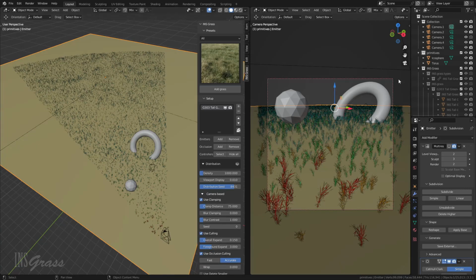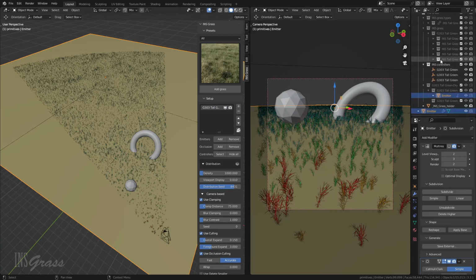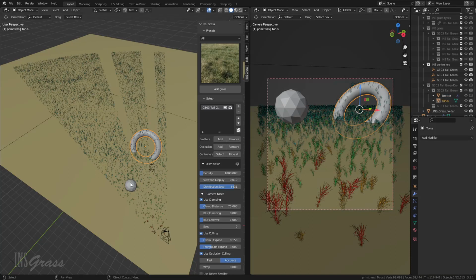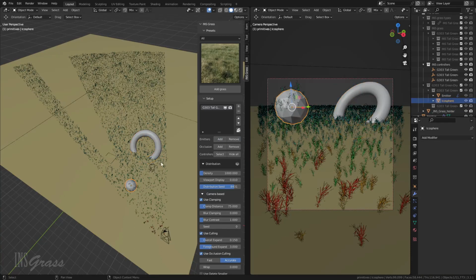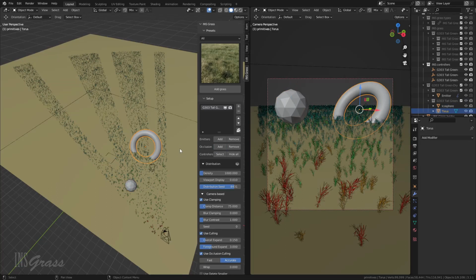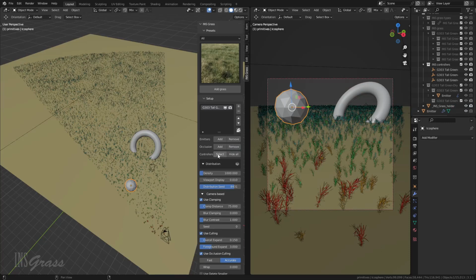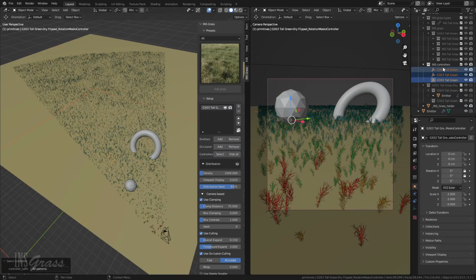When I've added grass, INS Grass has created a collection in the outliner. Things in the collection have gray color, which means that all data from the add-on is linked with your file. So INS Grass elements will not increase its size. Here you can also check which scene elements are assigned to a specific grass type. When I add emitters, they show up in the outliner. Occlusion objects also have their own collection. The outliner is very helpful when it comes to managing pattern controllers.